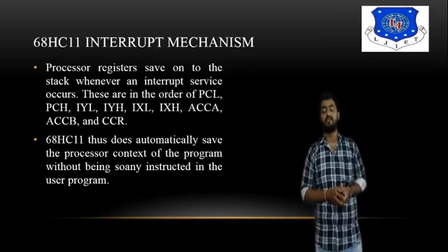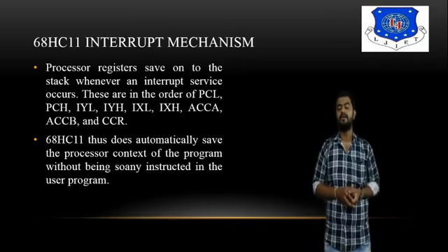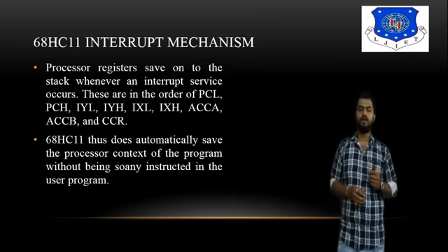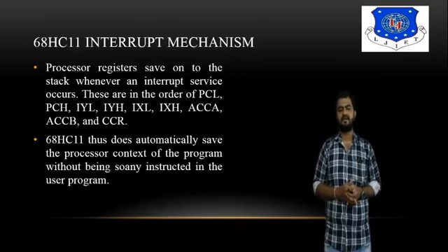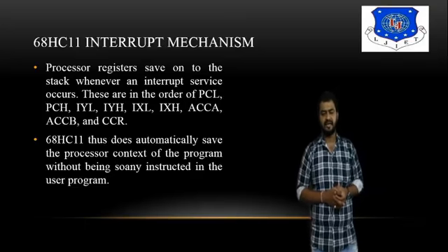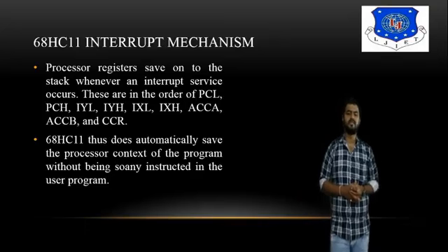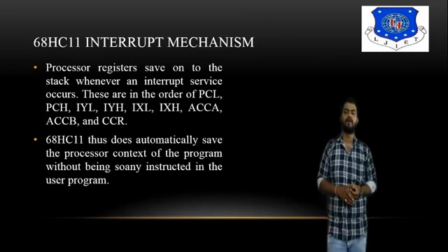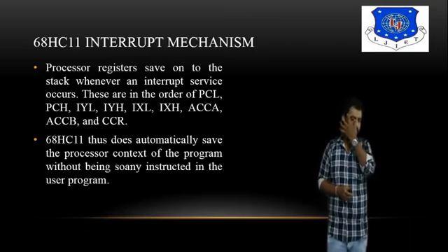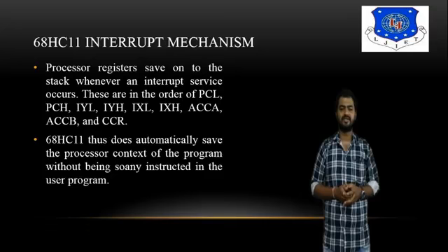Now, the 68HC11 interrupt service mechanism. This one is a very popular microcontroller in those days. Basically, we are focusing on Motorola. Right? So the processor registers are saved on the stack whenever an interrupt service occurs, in the order PCL, PCH, IYL, IYH, IXL, IXH, ACCA, ACCB and CCR. So basically, in that case, we focus on the higher and lower bytes of the registers, and we are considering the processor instruction set, meaning we are talking specifically about the processor instruction at that time.